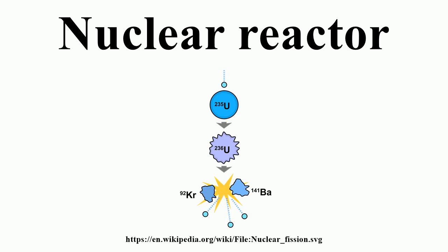Cooling. A nuclear reactor coolant, usually water but sometimes a gas or a liquid metal or molten salt, is circulated past the reactor core to absorb the heat that it generates. The heat is carried away from the reactor and is then used to generate steam. Most reactor systems employ a cooling system that is physically separated from the water that will be boiled to produce pressurized steam for the turbines, like the pressurized water reactor. However, in some reactors the water for the steam turbines is boiled directly by the reactor core, for example the boiling water reactor.